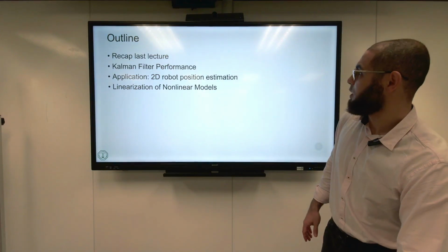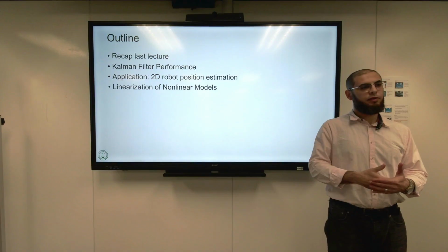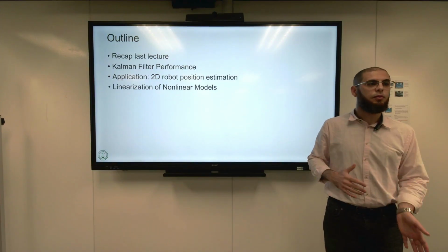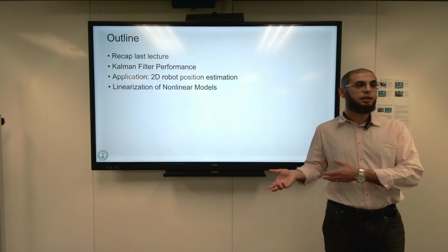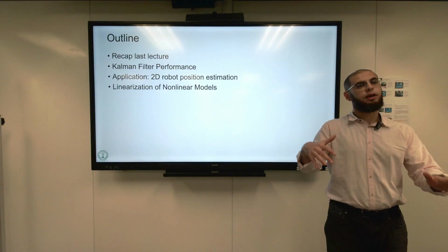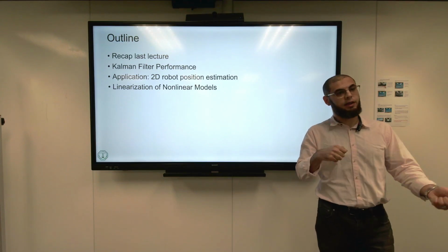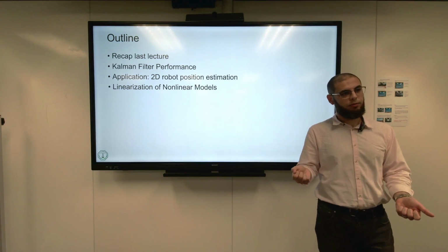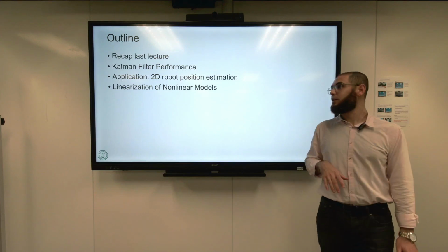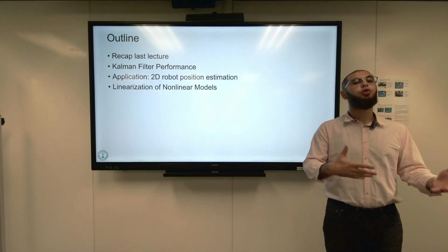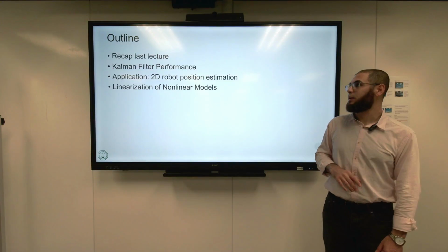So today, inshallah, guys, we're going to be looking at the performance of a Kalman filter. After you implement the Kalman filter, you've seen that in the end, there are just a few equations that we implement in the code. If you take the sensor readings, whether they're proprioceptive or exteroceptive, and connect them in a simple way to the Kalman filter algorithm, you need to define the state transition model and the measurement model. So that's your job to actually identify all of this. And afterwards, you just tune some parameters. So today, we're going to be seeing how some parameters affect the performance of the Kalman filter.